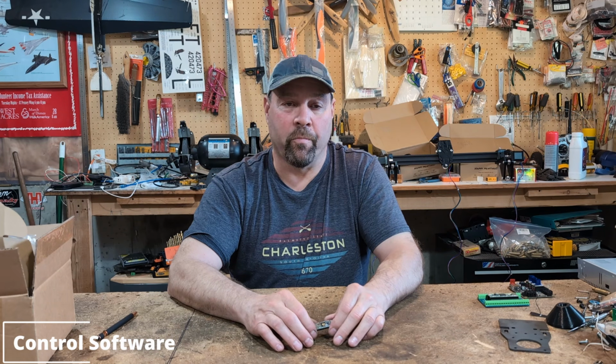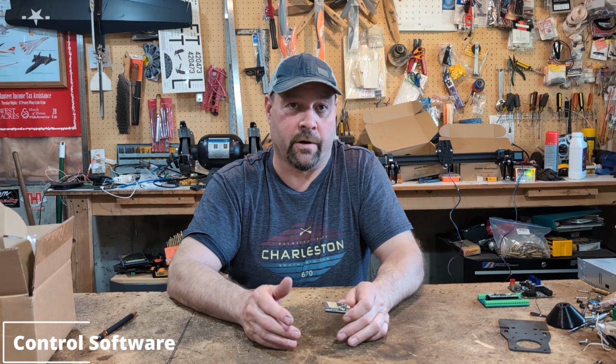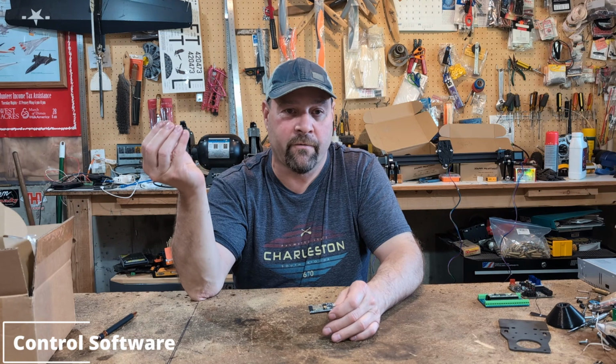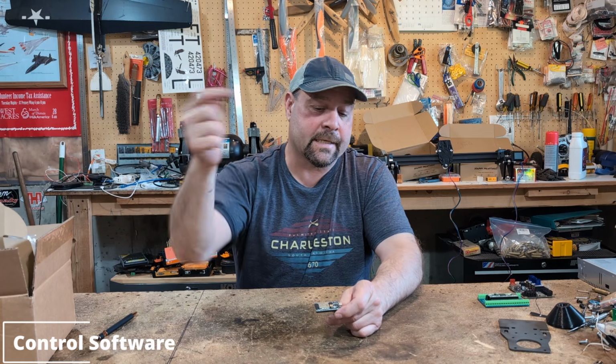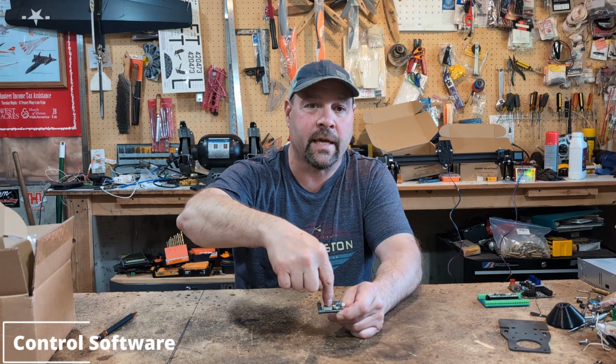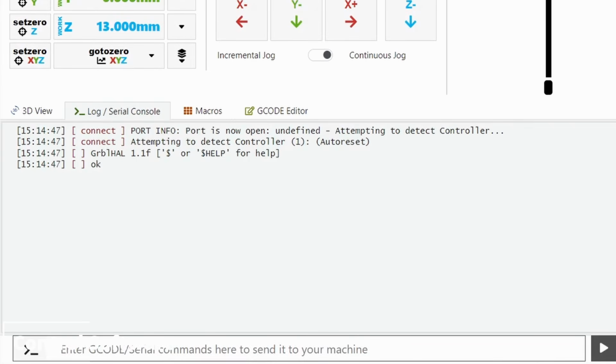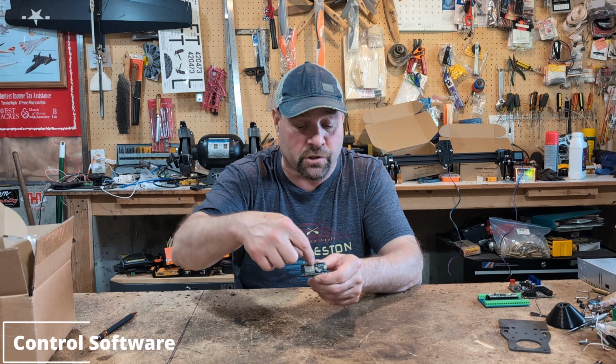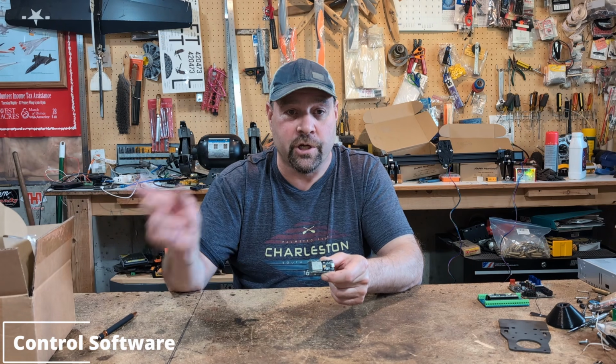So what is Openbuilds Control? Well, Openbuilds Control is a G-code sender. So that's all it does. It takes that G code that we created from the post processor and it sends it into the ESP32. That's all it does. You know, sure, you can move to home position, you can move a few things around, control the machine a little bit, but its primary function is just to move the G code to here.